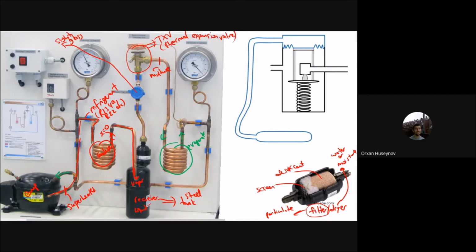For the evaporator part of the heat pump or the refrigeration system here, it takes the Q in. It will need Q in because evaporation here is very similar to, exactly the same as, the boiler. So here you have the boiling process. The refrigerant changes phase, and for this boiling process you will need some heat. That heat is Q in. For the condenser, it was superheated at the beginning and it becomes saturated, and therefore you will have that Q out.